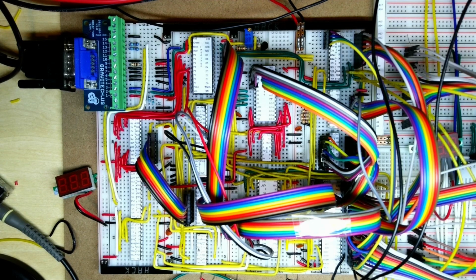Now what I'm going to do first of all is to try the original test program. So test 4 was the last one I used. Now this doesn't know about the control register, so I would expect it not to display anything initially because the video enable is not going to be set. So video enable is this output down here. And what I will do is once I've run it, I'll switch it between this pin and this pin, which is the inverted one. And I should then be able to see that.